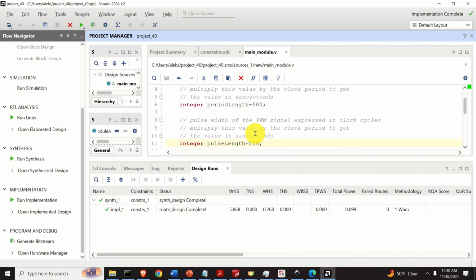And again, be patient. Meanwhile, attach your FPGA to your computer. For that purpose, you need to use the UART to USB cable, and after I attach, you will hear the sound. Here it is, it's attached, while over here the write bit stream is still running. I will also turn on my oscilloscope such that I can see the signals. And let's again be patient and wait for a while until the bit stream is being written.